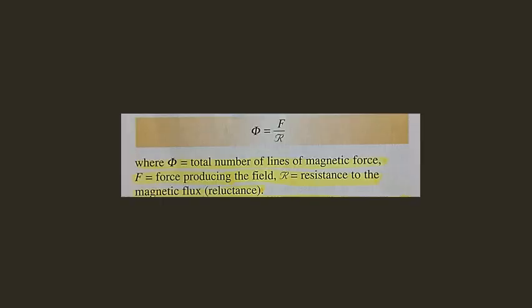Magnetic circuits. A detailed study of magnetic circuits is beyond the scope of this text. However, you should know the terms used to describe the quantities and characteristics of magnetic circuits. Reluctance. It has already been mentioned that a likeness exists between magnetic circuits and electrical circuits. In addition, a law of magnetic circuits exists that is comparable to Ohm's law for electrical circuits. This law is known as Rowland's law. Rowland's law states that the number of lines of magnetic flux, comparable to the current in electrical circuits, is in direct proportion to the force, comparable to voltage in electrical circuits, producing them.